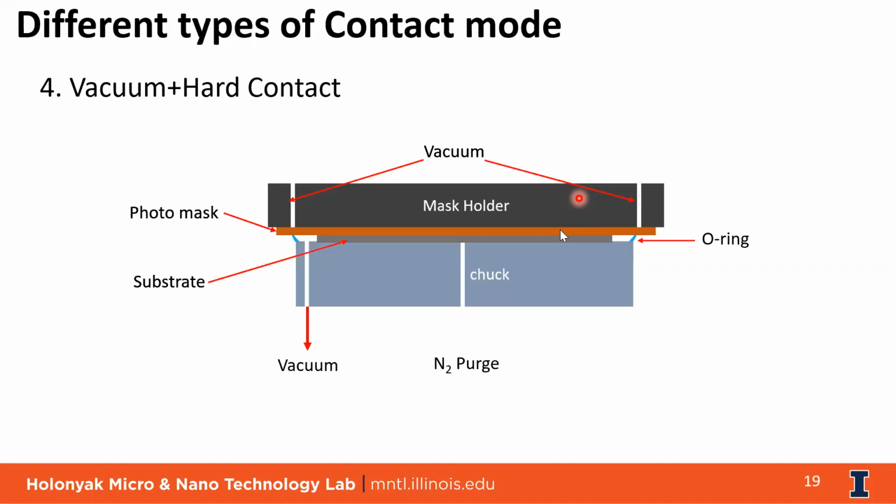Is there a way to remove edge beads to get better contact between your mask on small chips? Can you comment on managing edge beads on odd shapes and making good prints? Okay. So for a smaller substrate, you'll anyway get edge beads. In order to remove them, you can use solvents and Q-tips. You can slowly wipe the edges to remove them. So that's one way.